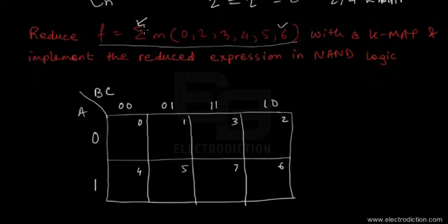Okay, so now the sigma sign, as I said earlier, basically denotes that the Boolean function is an SOP type function, which means it's a sum of products. Over here, any complementary quantity is represented with the value of 0. So here 0 represents a complementary quantity, while 1 represents a non-complementary quantity. And whenever we're working with a SOP type function, whichever cell numbers are present in the function, we are supposed to put a 1 over there.